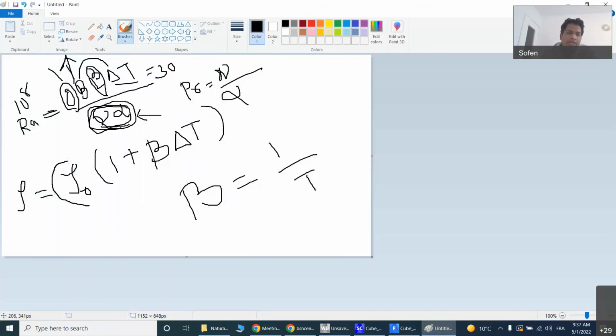This is the specific operating density because the buoyancy force in the Navier-Stokes equation will become rho minus rho 0 into g. So convection will take place whenever there is a difference of density from the reference density, right? This is known as the operating density.